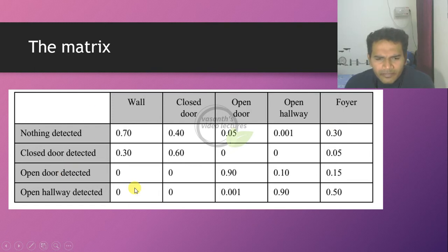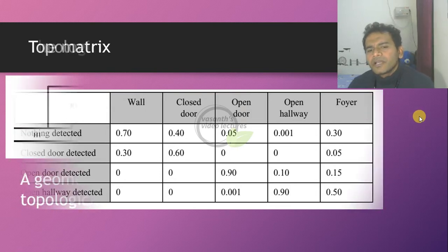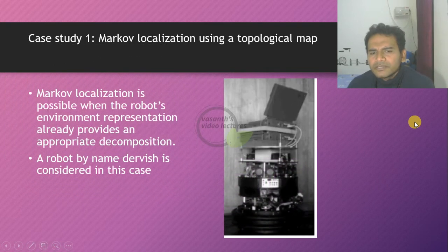So like this they have determined individual possible things. So if you check whether the door is open, it is yielding a result 0 because there is a wall there. So that means whenever the wall comes, a door cannot be detected. Similarly, the other possible conditions. So like this they have derived multiple solutions for multiple cases in the case of a topological map approach using the Markov approach, that is the Markov localization technique.